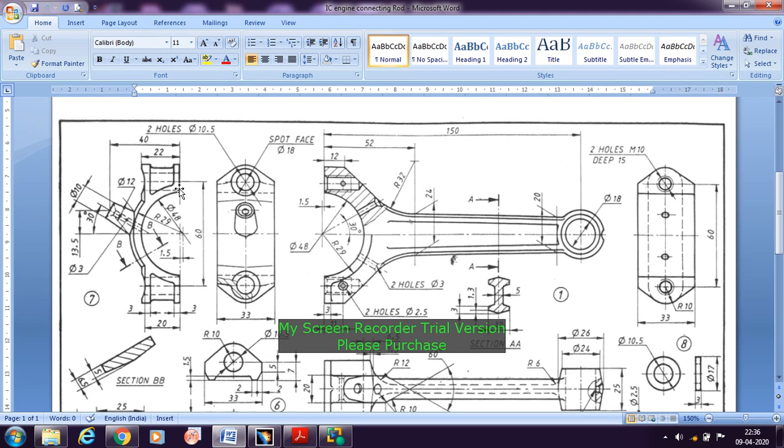Now you need to take the vertical height as 40 here, and then form this profile. After taking the 40 here, you need to know about the thickness. It's not given, but when you check in the bottom, it is given as 3 mm here. So take the 3 mm and then draw the vertical line until it touches the circle. Then you need to draw one more vertical line here. For that the distance is given. Here it is again the thickness as 3 mm, and then there is some extra portion which is given, so we will take it as 1 mm. 3 plus 1, 4.